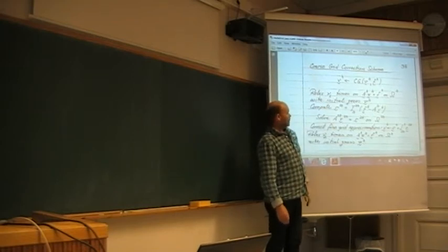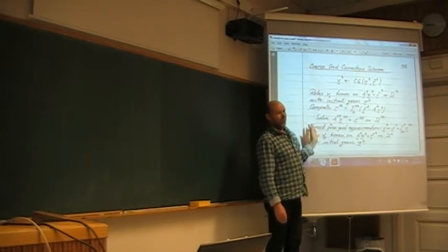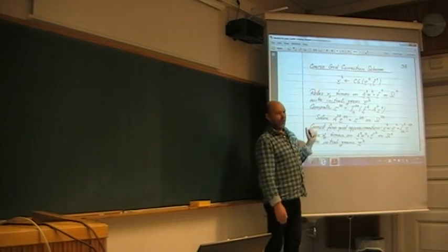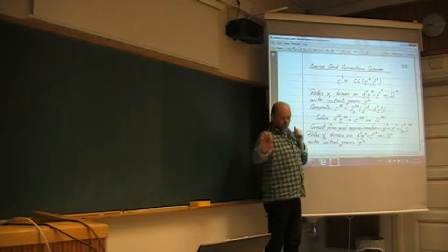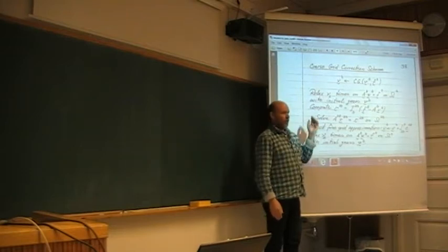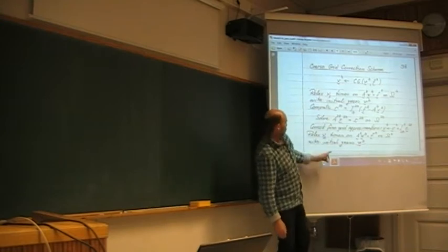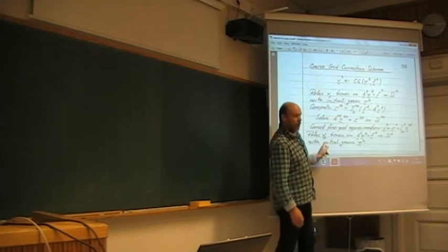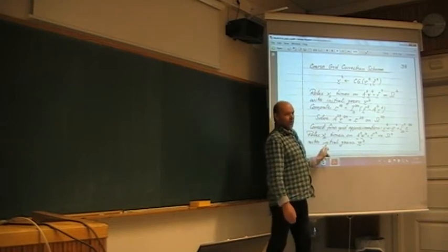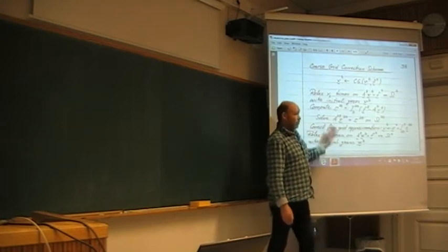And this is also the reason why we go through this theory, because you as users of CFD programs will say, use multigrid. And then the program will ask you, what cycle should I use? What is nu 1? What is nu 2? It will ask, and then you have to tell it. So you have to know what you're dealing with.